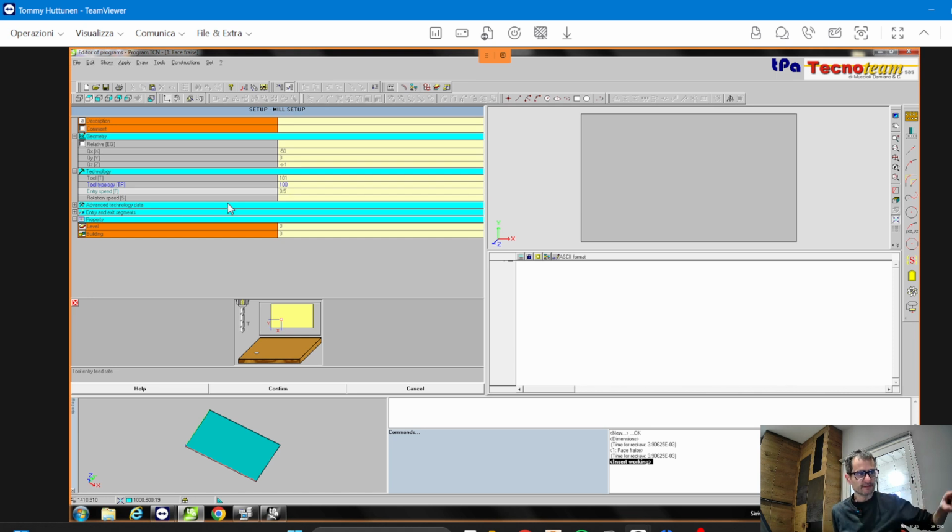When you have moved the tool inside the wood and you are already at the depth, you can increase the speed, no problem. But when we go inside in this way, slowly down. And we speak about the tool, I repeat, in another lesson. Rotation can be between 3,000 up to 22,000, the range. It depends on the tool, I repeat, and some parameters. For example, it can be 18,000 RPM, a medium speed of the spindle.